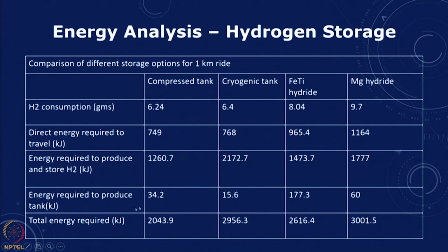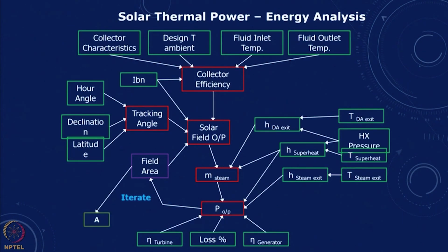That depends on the performance, and for an equivalent amount of performance, we can compare. Right now, the compressed hydrogen tank seems to be the best option from an energy point of view. Of course, there are issues in terms of safety, and solid state storage is better for safety.